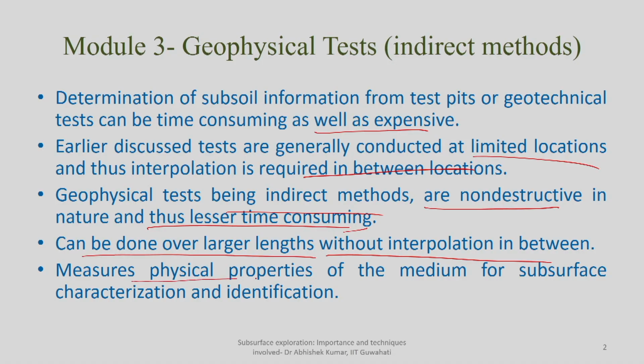So, it measures the physical properties of the medium, so that you can go for subsurface characterization, even identification. At times it is not only used for identifying different layers, it can also be used for identification of buried objects, it can also detect some unconformity, and in archaeological surveys also geophysical tests are very prominently used.